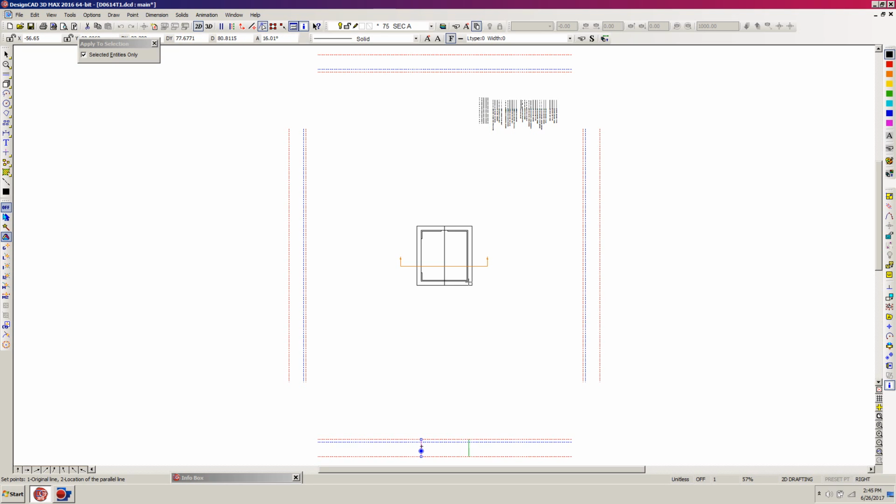So I'm going to right click on this far right corner, and that sets this line, and it's aligned with that lower right corner. Now I'm going to do the inside of the wall line. Even though there's a doorway there, I still want to know where the inside of the wall line is. So I'm hitting parallel, equals, again, and I'm going to right click on the inside of that wall, and I'm going to do the same thing on the next wall. So I'm going to hit the equals key again and click near that line, and again move over to the inside of the wall on the right hand side and right click, and it'll gravity snap and set a point, which establishes that parallel line.